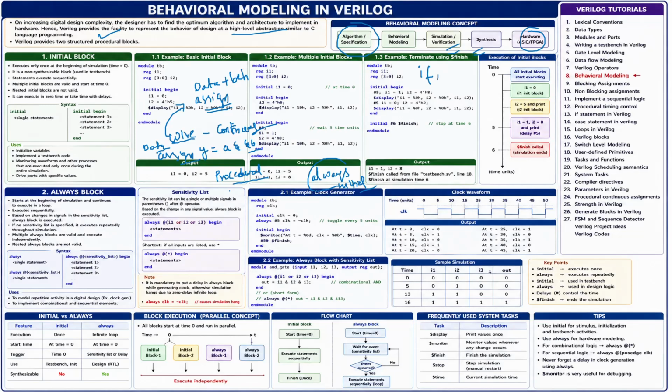What is the use of the always block? Whatever the conditions you are taking and whatever the simulation you are taking, it executes continuously. So it depends upon the condition of the statement. Because always is the statement, inside that always begin we use some statements. What statements we use depends on the multiplexer you are designing. In that multiplexer, what are the inputs you have?